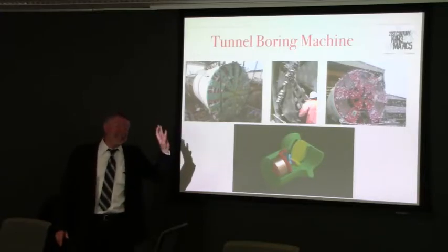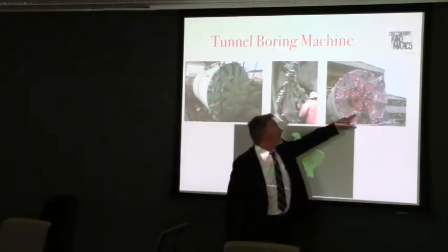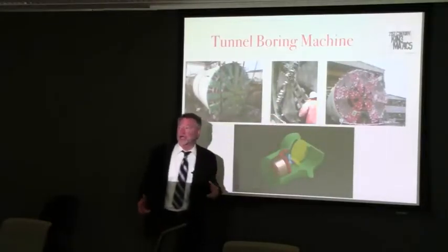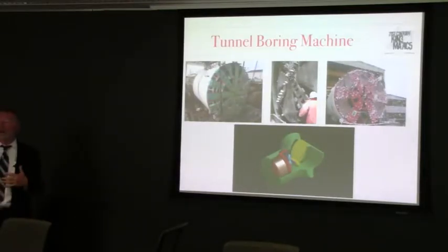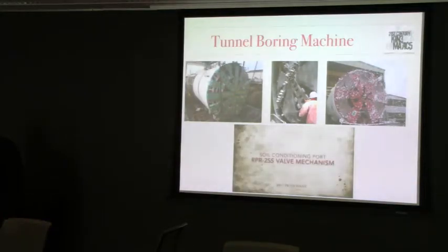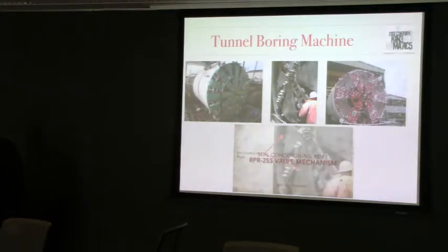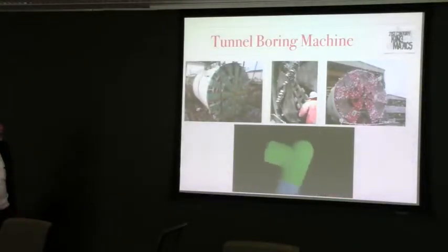And it turns out that it has a standard problem: those ports, you can sort of see the ports here, for example, and in here, those ports clog. And so it's a constant calculation in a tunnel boring machine, how long I've been doing the boring and at what point I'm going to stop so that I can clear the percentage of ports that I know are clogged. That's an enormous task. We came up with this design working with a colleague in Germany who's in the tunnel boring business. So those are the soil conditioning ports.